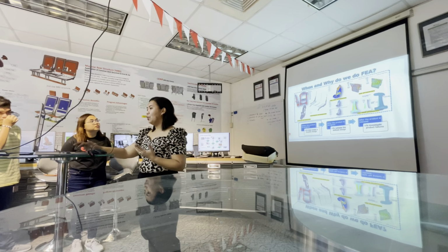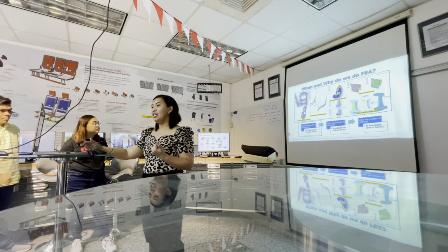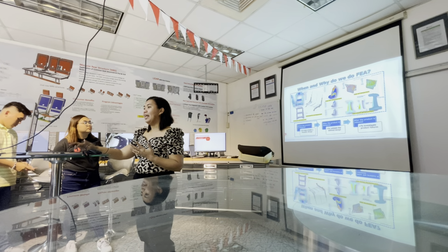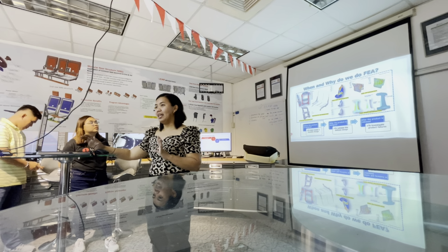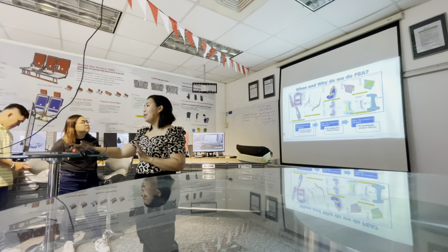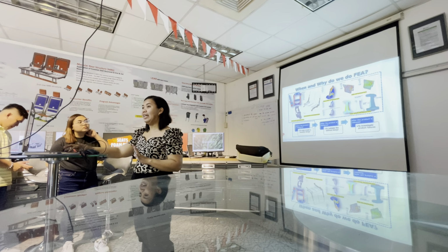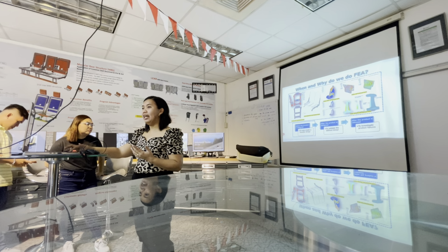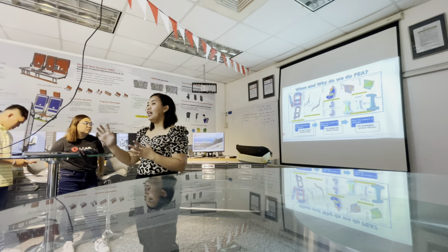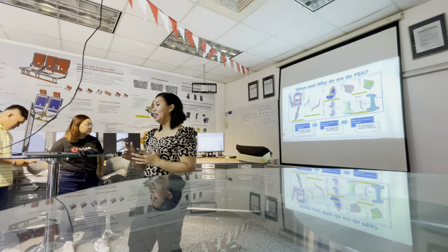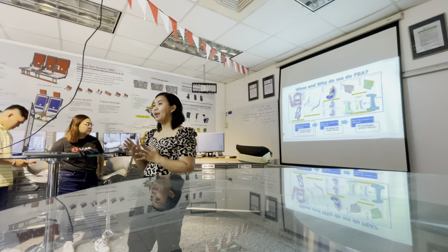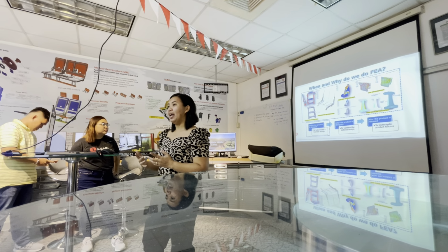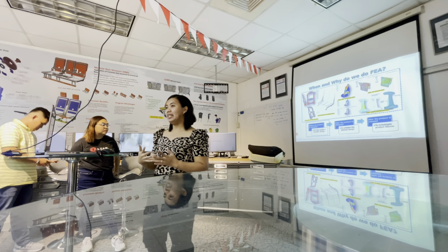And the last one is the free shape optimization. So this optimization is used to identify the stress concentration areas. As you can see, by just merely changing the radius of this clip, we can reduce the stress concentration in the clip. So these are the optimizations, or these are the FEA that we are doing prior to CAD design, so that we can help the designer create a more feasible CAD design.